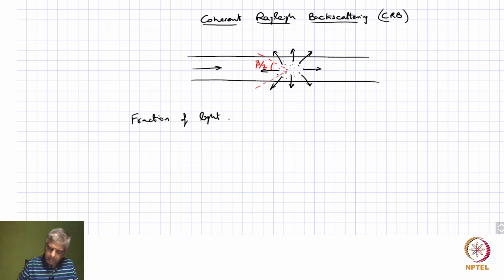So, when you look at the area of the solid angle, or specifically the fraction of light collected, that can be approximated as (beta/2) the whole square, because it's happening in both directions. So, that can be approximated as beta square over 4, where beta corresponds to the numerical aperture of the fiber, which once again is determined by the contrast in the refractive index between the core and the cladding.